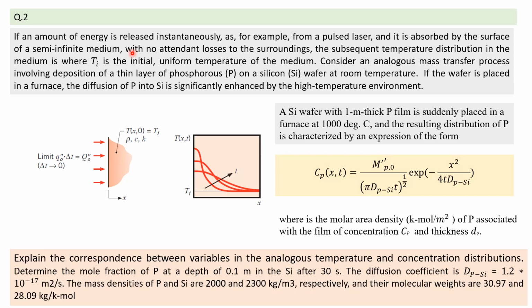Suppose you take a wall which is very thick, and we supply some heat to its outside. As soon as the heat enters, it will only penetrate up to a particular length. After that, all that effect will be lost. It will gradually diminish. So after a particular length, there is no meaning in actually conducting the study. Such mediums can be said to be semi-infinite.